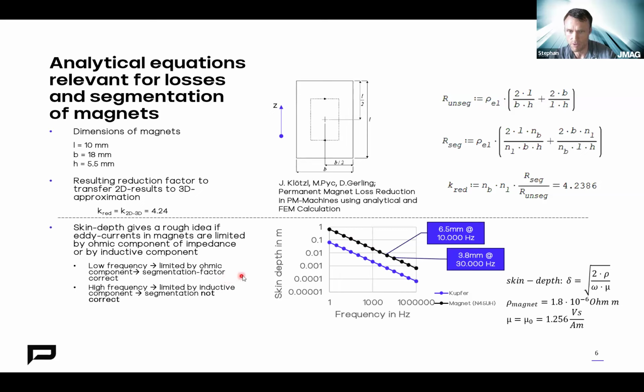And this is because of the limitation of this eddy current by the ohmic component and an inductive component. In the end, to evaluate if this is the case for the e-motor design and for the operating point of interest, you can use the skin depth.